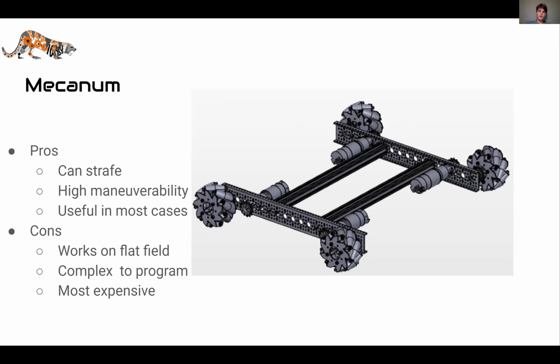And that can be used if you drive those wheels against each other. Those rollers will actually slide the robot along the direction that those rollers are facing. And you can get strafing or side-to-side movement, but you still retain a decent amount of traction. So good things about these, it's only four wheels, four motors, high maneuverability, pretty decent traction.